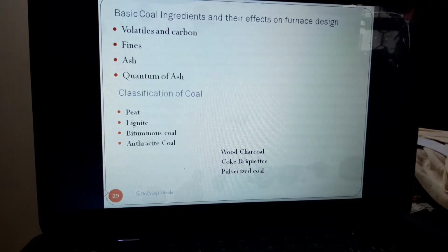This peculiar behavior of coal is called caking. At 500 to 600 degrees centigrade, the plastic mass gets solidified again, forming a mass with holes within the coal. At this juncture, the rich hydrocarbon gases, which are nothing but volatiles, get released from the mass. The volatiles which are released need additional air to burn, as the primary air leaving the bed is used in coal burning. This is generally done by supplying secondary air over the bed through a number of passages which are located above the fire bed.